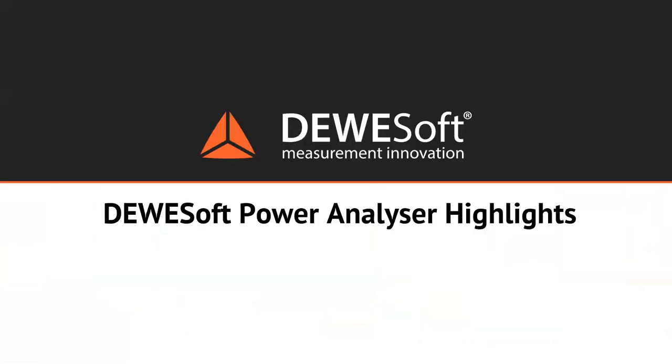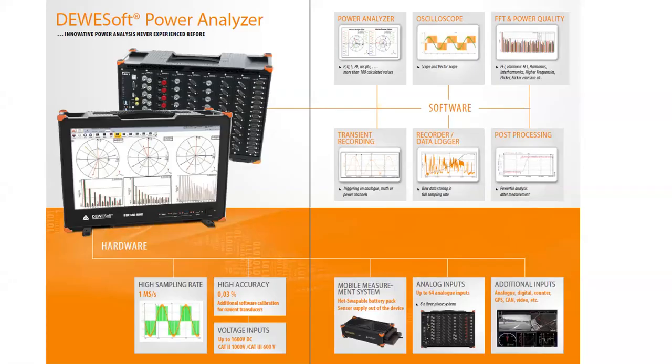So let's talk about the Dewesoft Power Analyzer highlights. On the left-hand side, we have the hardware. With 1 megasample per second, we have the high sampling rate. We have also high accuracy with 0.03% of reading, and our voltage inputs are up to 1600 volts DC. We have the safety category 2 1000 volt and 3 600 volts.